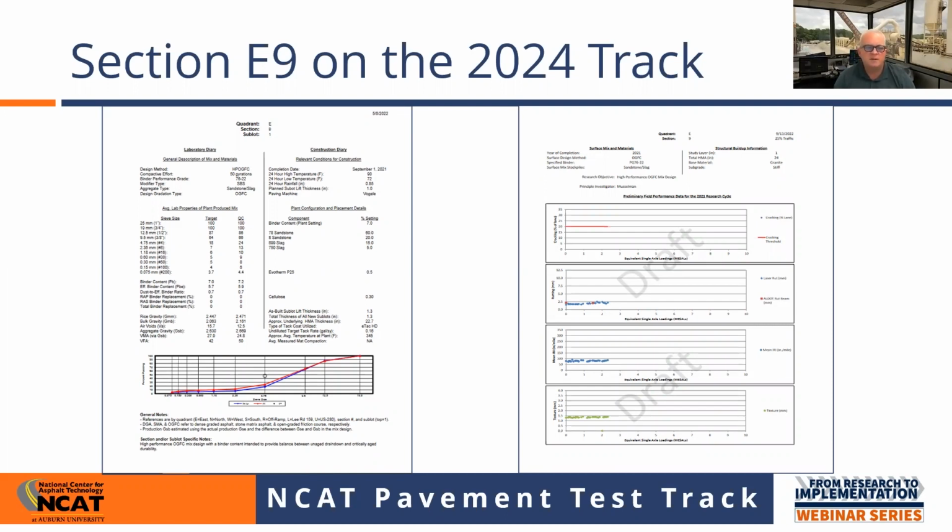It was a really good mix. This was a mix that, if it was subjected to the standard oil-based design procedure, would have come up with an optimum asphalt content in the low 6s, which is a typical historical value. This design actually came out at 7, and when we ran it with the plant setting on 7 and tested in the lab, we actually got closer to 7.2.